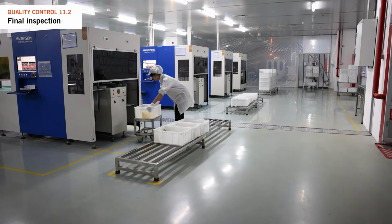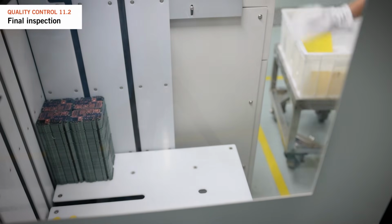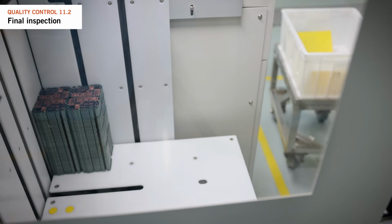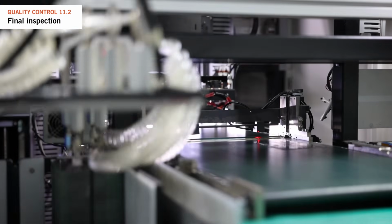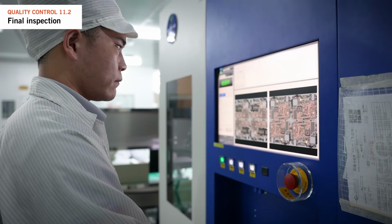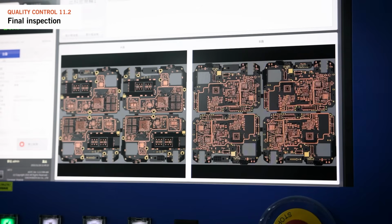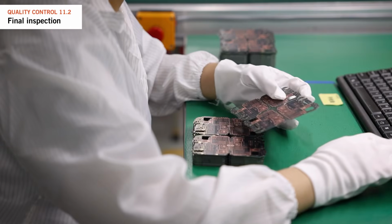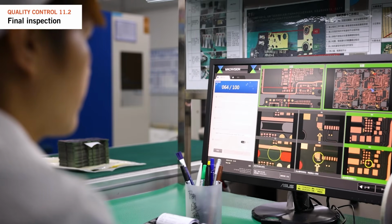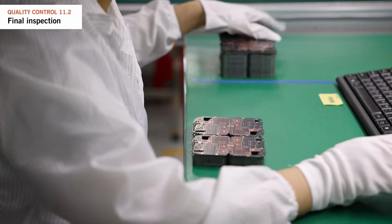After going through all production process steps, each PCB must be inspected to ensure that it meets the demands of the customer, IPC, and NCAB standards. The first step is the visual checking, where we are looking for any cosmetic defects or damage to the PCB that could affect meeting the agreed demands or pose a risk to product functionality.